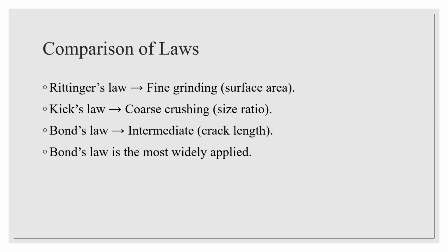Now, comparison of these three laws. Rittinger's law is very useful for fine grinding and is based on surface area. Kick's law is very useful for coarse crushing and is based on size ratio. Bond's law gives the best result for intermediate grinding or crushing, and it is based on crack length. So Bond's law is the most widely applied for the calculation of power requirement of size reduction equipment.